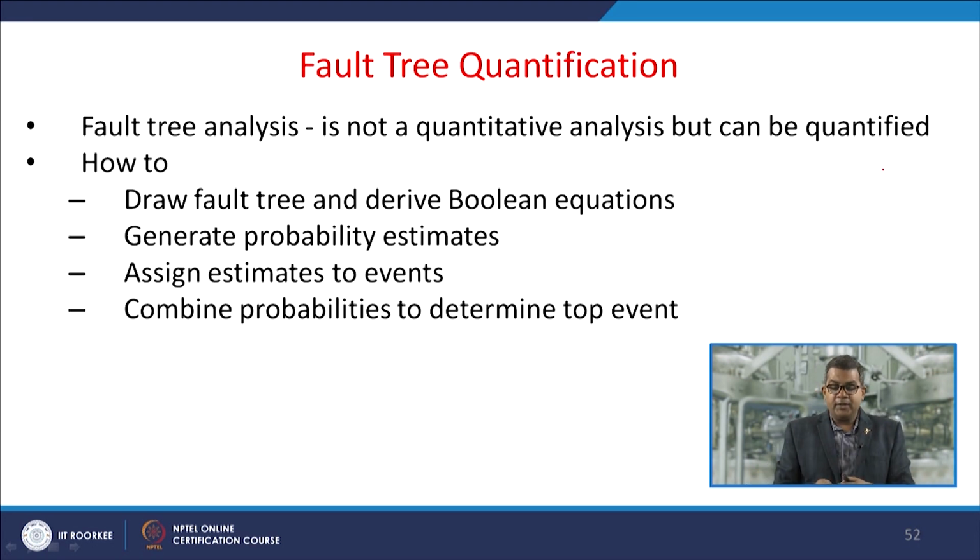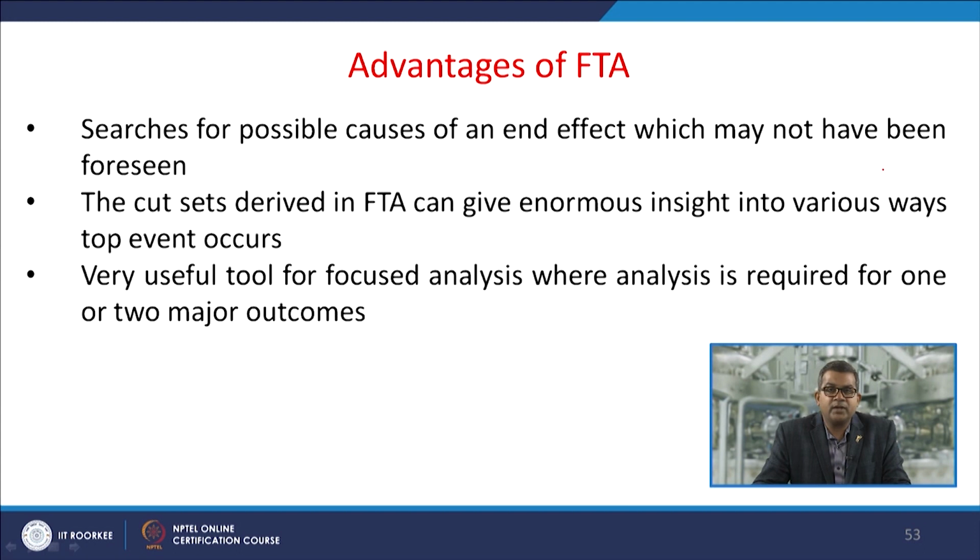Now, the fault tree quantification: this analysis is not quantitative analysis, but can be quantified. So, the question arises how to quantify this one. So, draw the fault tree and derive the Boolean equations, generate the probability estimates, assign estimates to events, and then combine the probabilities to determine the top event. So, this is the usual protocol for this quantification.